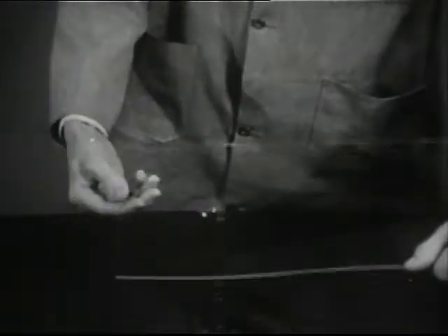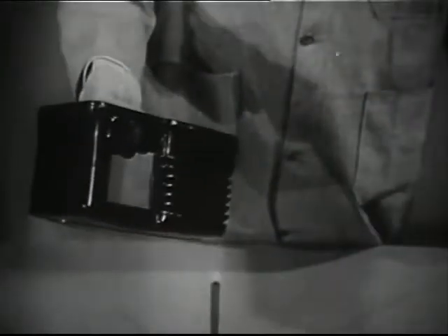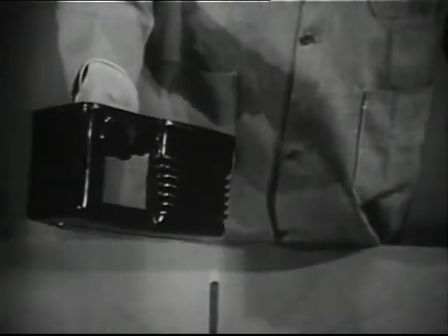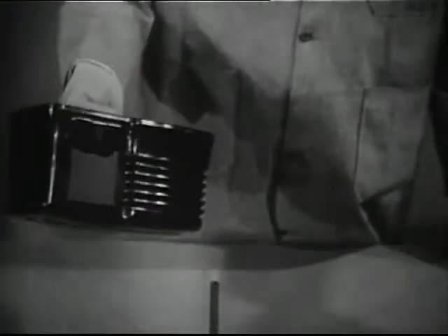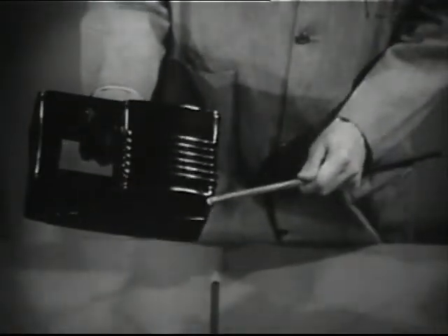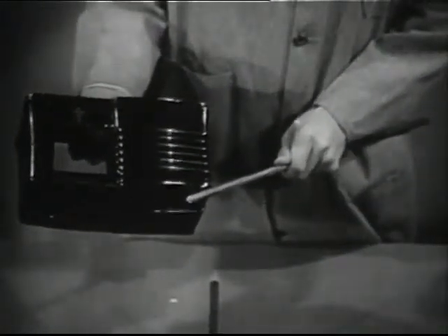A thermoplastic material such as this sheet, which is the same polystyrene from which the dial face was made, originally was hardened by cooling and can be softened by heat. It can then be reshaped and will harden again by cooling. A thermosetting material which hardened through chemical changes under heat remains as rigid as ever. It may char, but it cannot be softened or melted. Once formed and hardened, it can never be softened and reshaped.